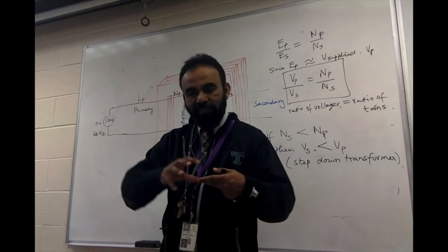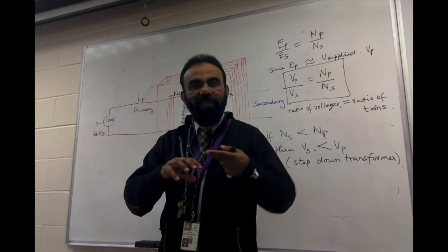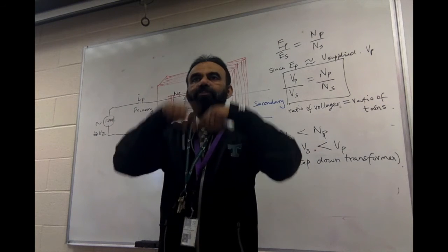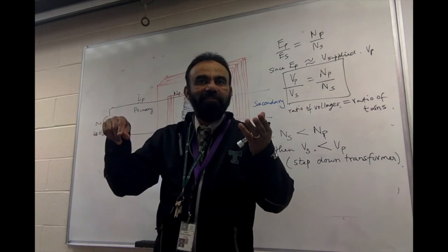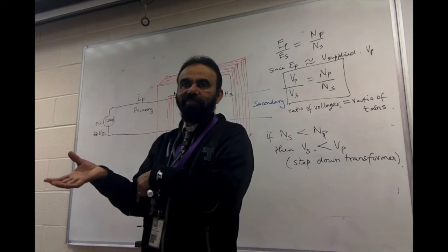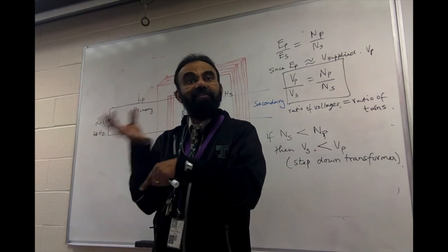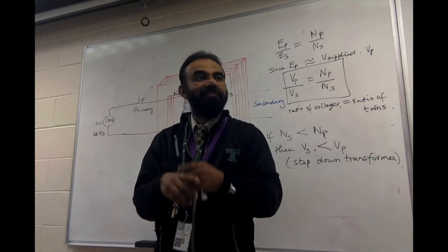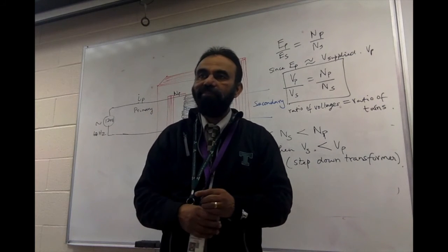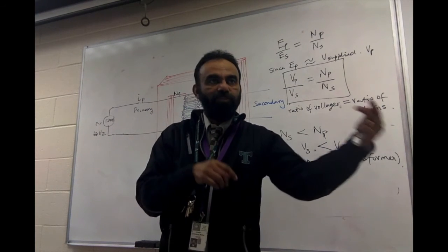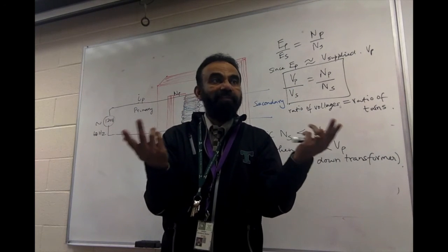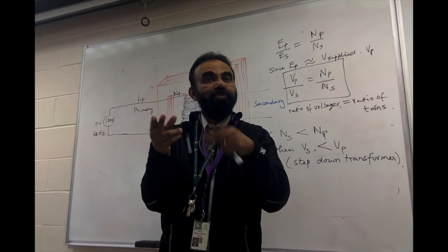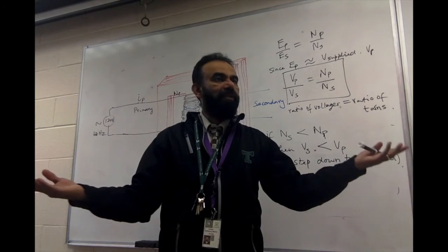And there's a circuitry which makes the 12 volt DC into 12 volts AC. Make sense? And then comes the transformer. And that transformer is step up. How many times? 10 times. So once you change the DC into AC, a transformer will work fine. And the output of the transformer is going to be 120 AC.